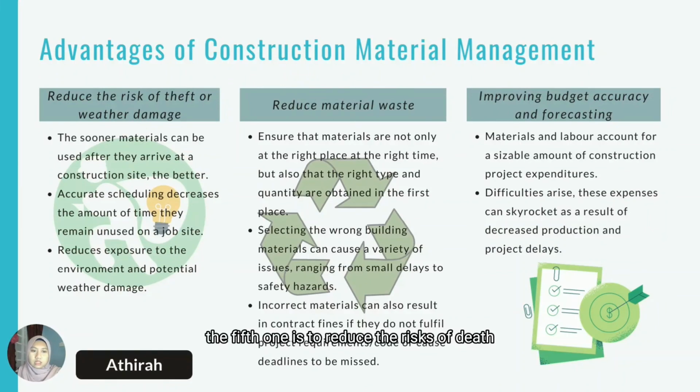The third one is to reduce the risks of theft and weather damage. It is better for materials to be used soon after they arrive at the construction site, especially when secure or weatherproof storage facilities are scarce.